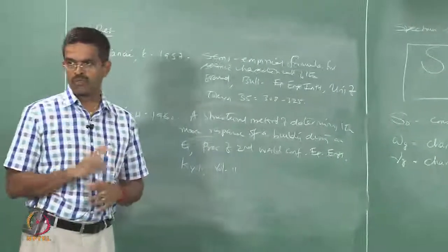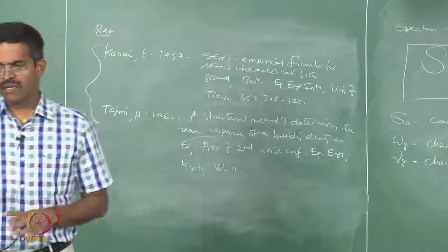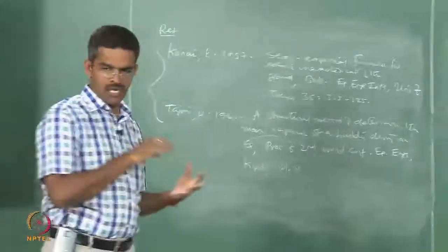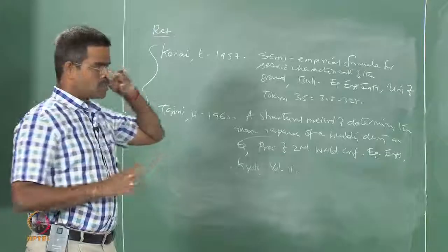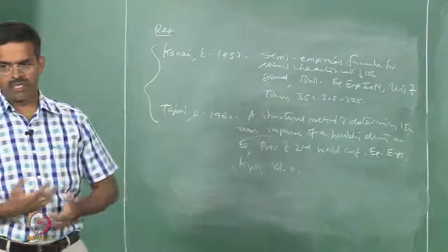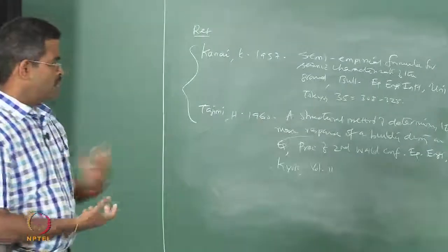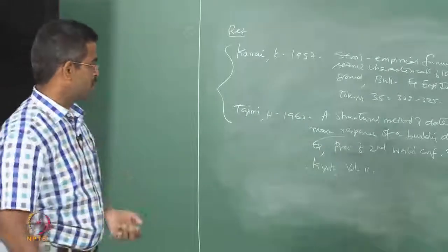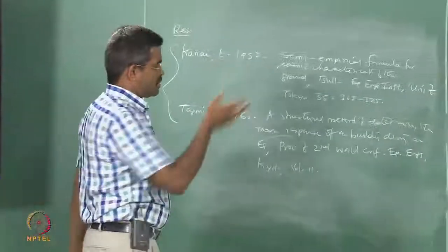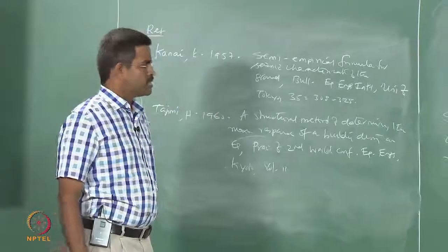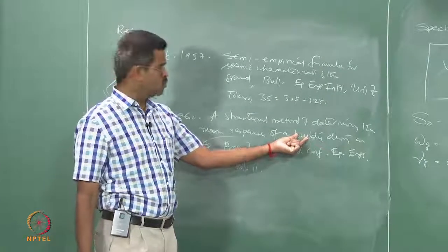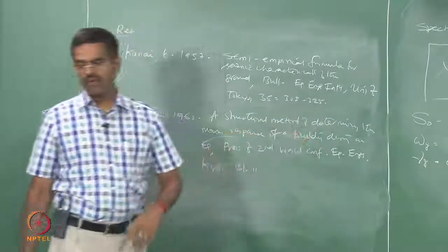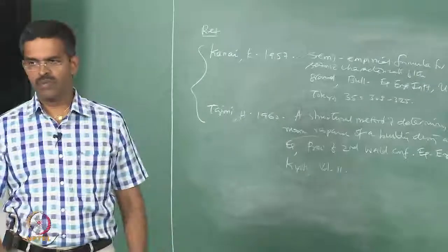We have discussed two issues here. One is the drag linearization. We showed you how linearization can be done and why it is necessary in a given system. Second is how to compute the earthquake forces caused by the ground seabed movement or the seabed displacement in terms of this power spectrum given by Kanai and Tajimi, which is known as the Kanai-Tajimi power spectrum, which is essentially applied for buildings, but nevertheless recent studies in offshore engineering have used this spectrum for calculating the forces in the given members because of seabed movement.